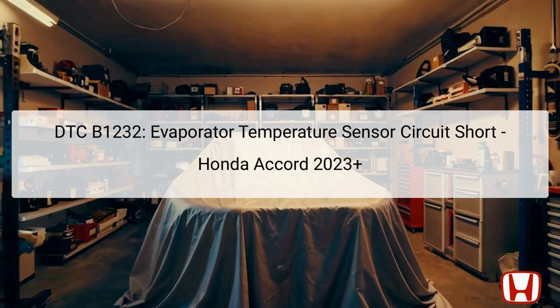When the input voltage from this sensor drops below a specified threshold, the climate control unit interprets this as an abnormality and logs the DTC in the vehicle's memory. It is crucial to address this code promptly, as it may lead to insufficient cabin cooling and potential further complications in the climate control system. This presentation will outline the components involved, possible causes, and detailed troubleshooting steps to effectively diagnose and resolve this error.